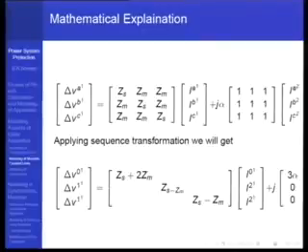This current here would give a zero sequence voltage on the other transmission line. You can show the same thing mathematically also. This is the circuit 1 voltage drop due to its own currents, and if I have transposed it adequately, then I can assume that all mutual impedances between circuit 1 and circuit 2 are equal to alpha: conductor A to conductor A, conductor A to conductor B of the other circuit, conductor A of the first circuit and conductor C of the second circuit, all such are equal to alpha. So this matrix is j alpha into 1, 1, 1.